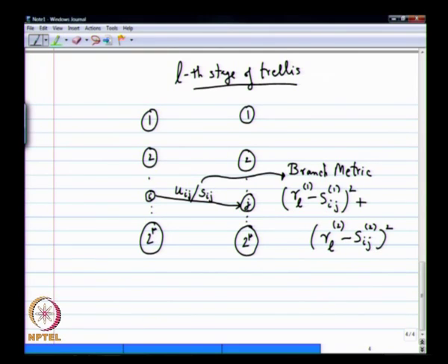Okay, so you have to think of this branch metric as some kind of a weight on that branch, okay, or some toll money that you have to pay somebody who is sitting there to go on this branch. Okay, to take this route you have to pay that money. Okay, so some cost associated with, or maybe the distance that you have to travel on that branch, some cost associated with that branch or edge or whatever you might want to call it.